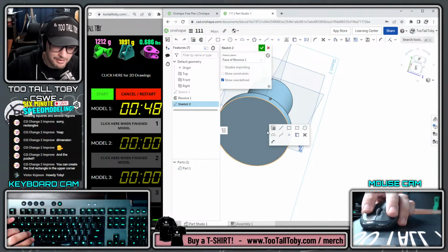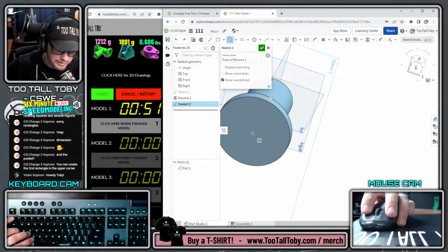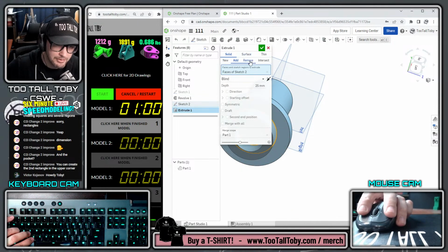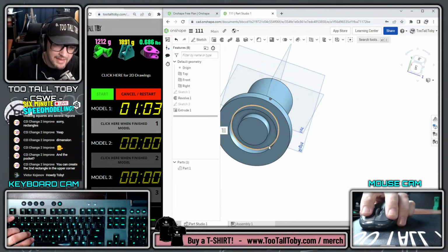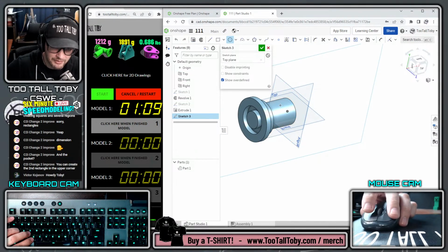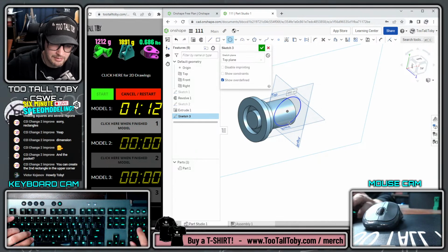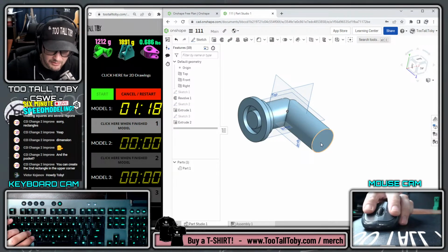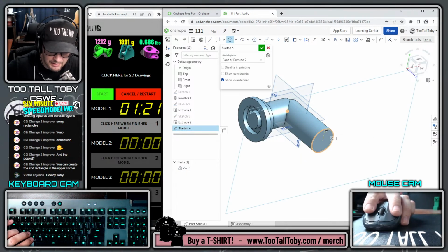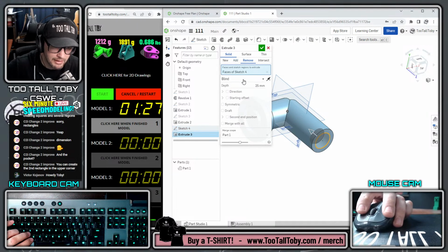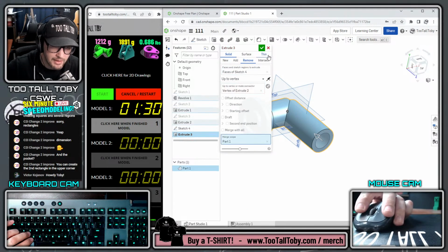And now for this end, I think what I'm going to do is create a circle here with a diameter of 80, and then another circle here with a diameter of 50. And then I'm going to extrude cut to the depth of 15. And then in the end, I can just blast this whole thing through. That's what I did in my little demonstration when I was modeling this part as a demo. So I think that's the way to go. So now this can be at 75 and can get extruded to 160. And then this can be 50 and extrude cut up to next, or up to vertex. There.